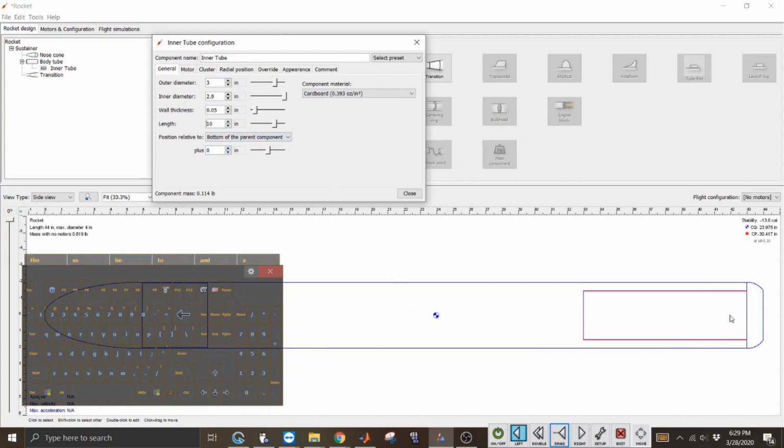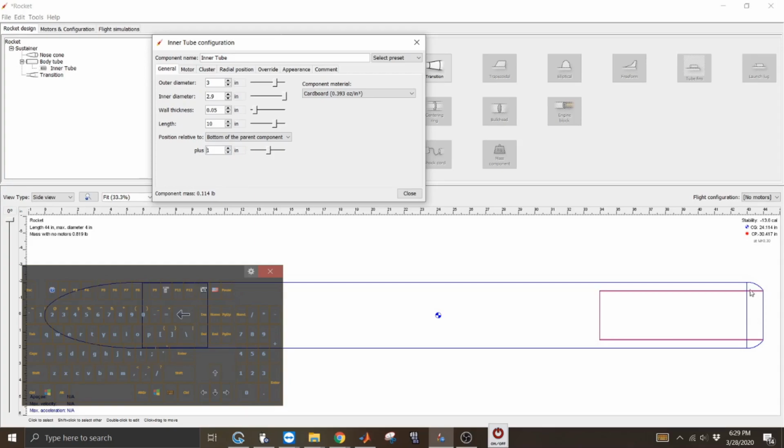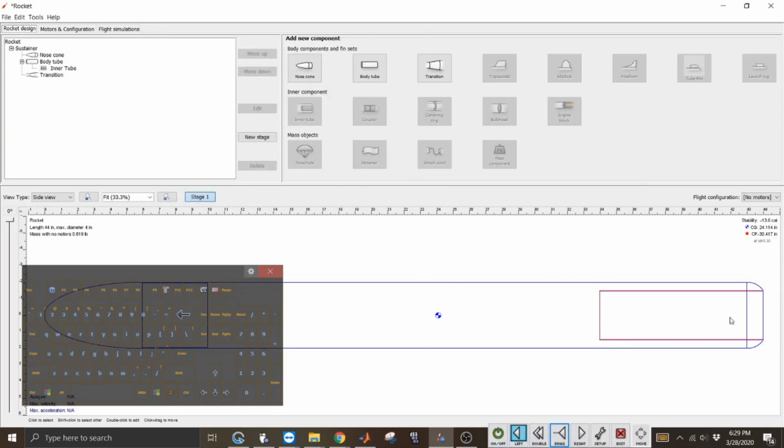And then I want this to be offset because the boat tail, we're pretty much gonna 3D print a lot of parts. And to avoid any exhaust from actually hitting this boat tail, we're gonna go the other direction so that this tube can sort of insulate the plastic 3D printed parts from any exhaust gases that may touch the outer edge. So that provides our inner tube.